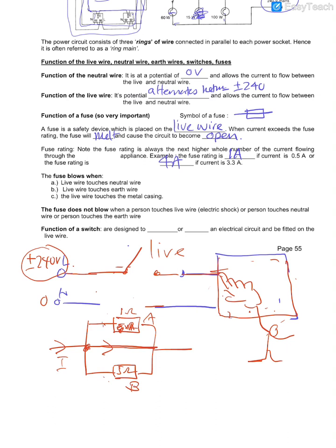Nothing will go through here, right? They will bypass. Everything will go through here, because there's no more resistance. So all the current will be here, and the total current will now be very large. Why? Because these two are no longer active. Okay, this is what we call a short circuit. So the current becomes very large. So any situation like this will cause a very large surge of current.